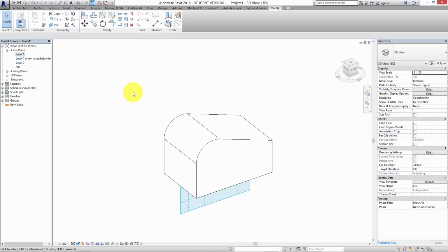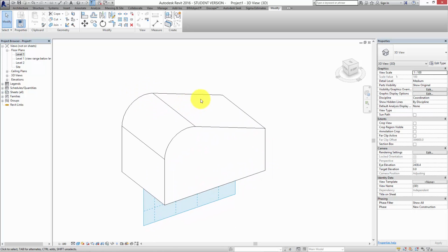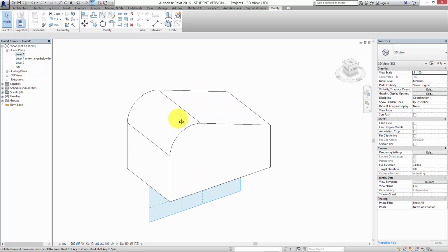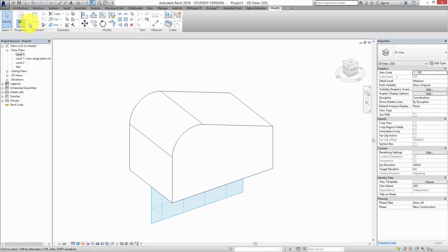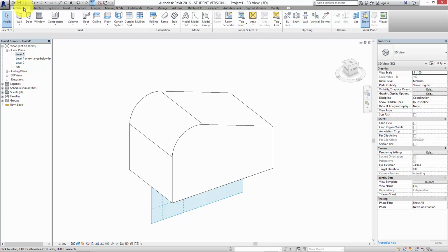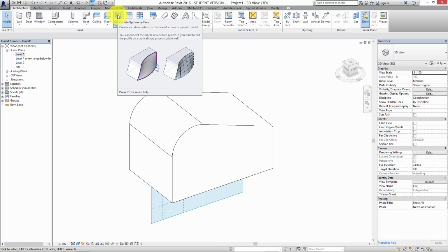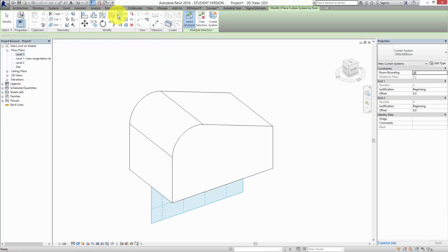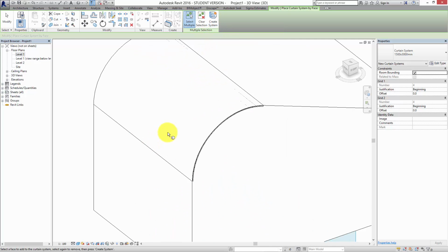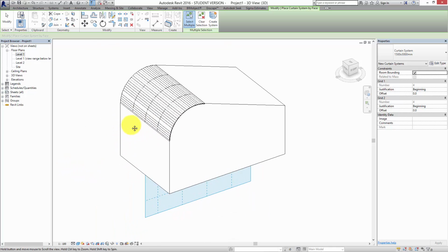And it's using these massing models that you can make kind of more complex forms than your standard stuff in Revit. So if I come into architecture here, I have something here called a curtain system. Now this is different to a curtain wall because it allows us to apply a systematic breakdown to a non-systematic mass. So if I select curtain system, I can select this element here, for example, and I can just press create system, and it divides it into elements.